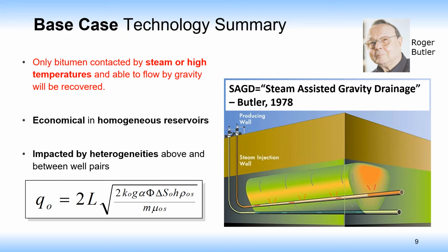And then we have porosity, a saturation type term that's also important because we have a lot of variation in saturation. The height of the net pay is right here, and that's what's quite variable. That's the focus of this talk, really, is on this term. Viscosity is very high to start, and the heating does lower viscosity, increasing this result.